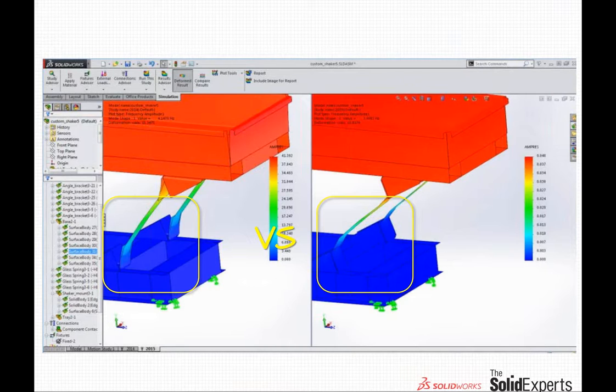However, this isn't practical to show in our model, and we need to be able to run a simulation on it. So previously what would happen, as you can see in the first image on your left, is that the edges of those gussets would start to separate from itself because the software couldn't handle that bonding situation when there was a gap.